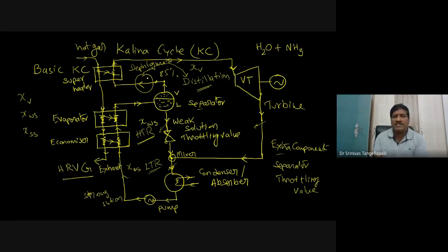This is also used in refrigeration systems. The dephlegmator removes some water part and sends it back to the separator, by rejecting heat to the surroundings. So by providing some cooling effect in the dephlegmator, the working fluid concentration is increased at the exit of the separator. In case this cycle is meant for a refrigeration system, let us say a vapor absorption refrigeration cycle, which operates in the reverse direction.